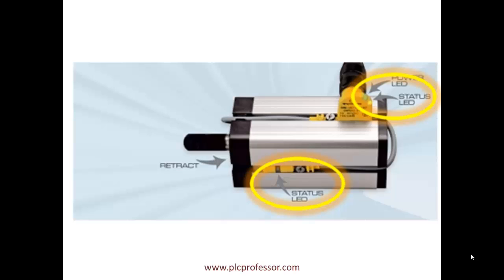In some applications, the piston doesn't actually travel all the way to the end of stroke because the rod, which you see sticking out the front there, is attached to tooling, and the tooling runs into a hard stop, and that is the position that you want. So you actually adjust the sensor to sense that it's where you want it to be at the end of that stroke. The sensors are installed in the correct location to sense the piston at each end of the cylinder.